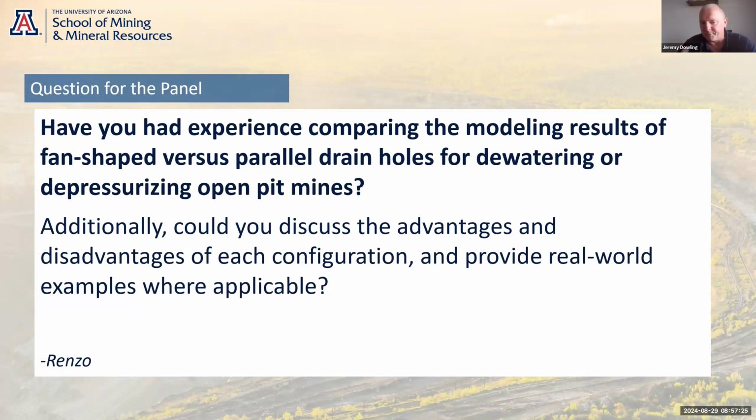So you can look at the depressurization response that the model indicates for different configurations of drains. It's easy to use the model to compare different configurations of drains. But similar to the tone of other discussions about the model, it's just a model, and the practical field data and the piezometric responses you get in the field are what you really need to use to guide and plan the drain drilling program.